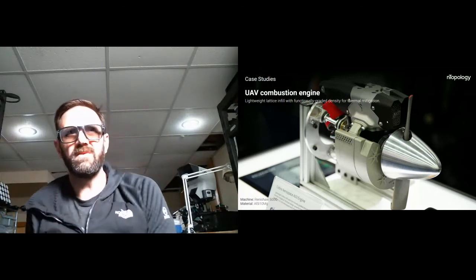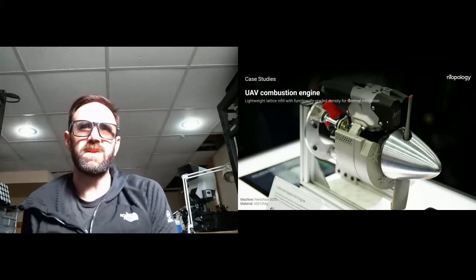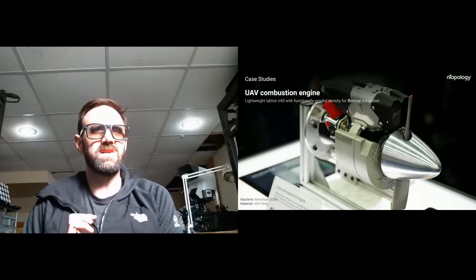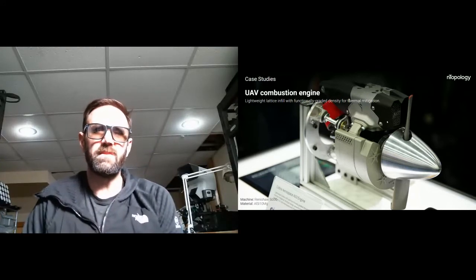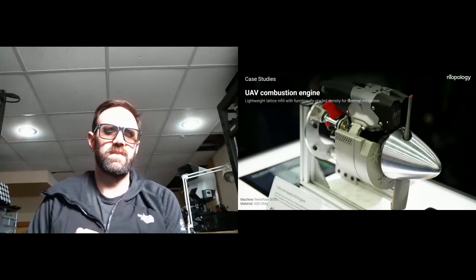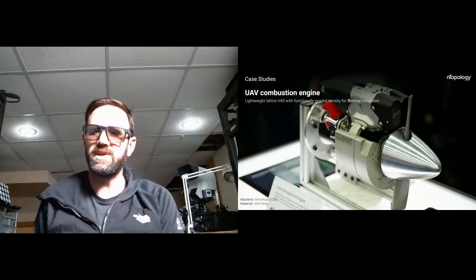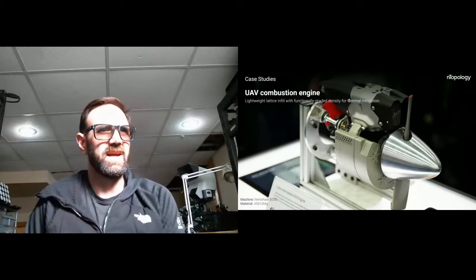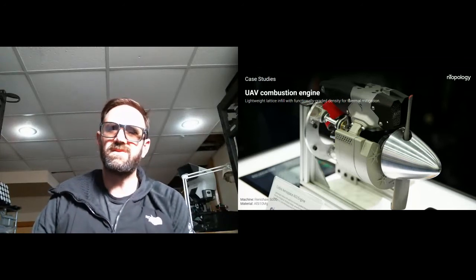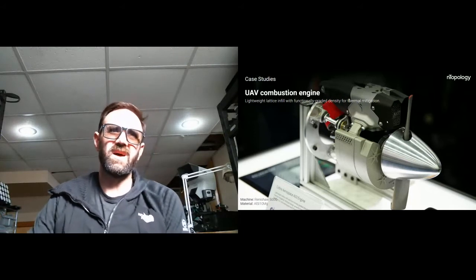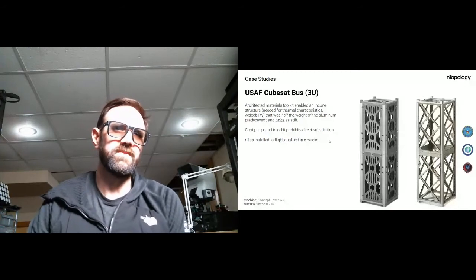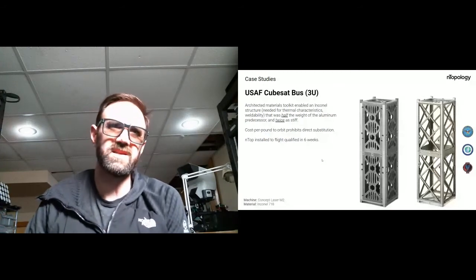Another one, this is more of a generic approach that's not algorithmic, but the idea is the use of a concept of a CubeSat, and then being able to make a digitally modular design and be able to print and manufacture that in a much tighter time frame than could be done by just ordering commercial off-the-shelf hardware. And so it looks like I need to update this slide. So nTop was installed, and this part was actually flight qualified within just under a week. It was fabricated in 2.5 days. The previous part actually had a 6 to 10 week delivery time.